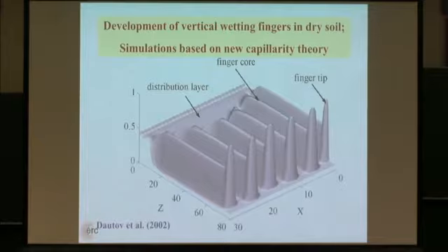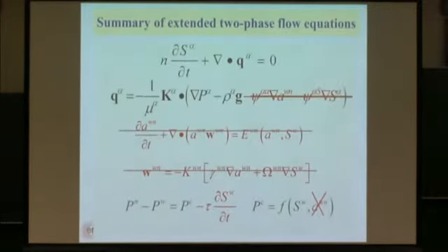What sets the tau, the time scale for this dynamical term? The tau has to do with the following. Remember the measurement of capillary pressure saturation curves. It's an equilibrium process. You change the capillary pressure, and then you wait. You look at the relaxation to the new equilibrium. If you are at equilibrium with a given saturation, given capillary pressure and pressure differences between phases, nothing is moving.